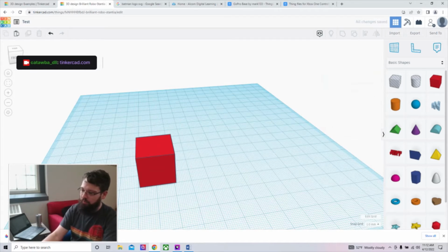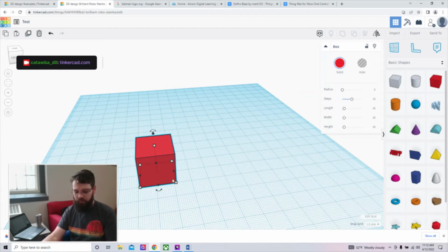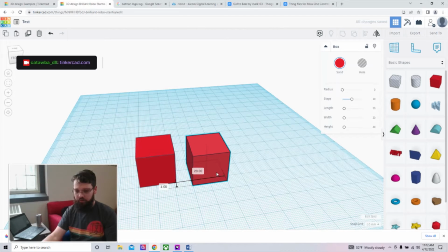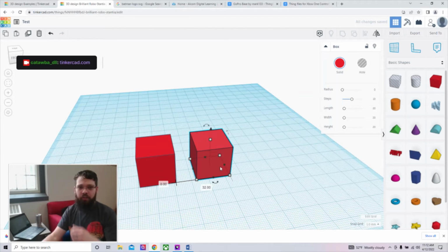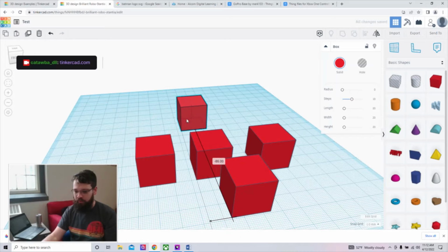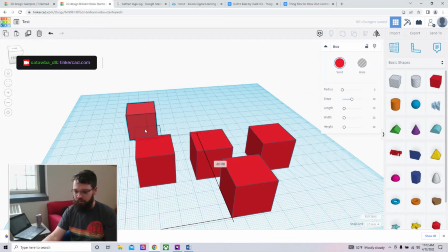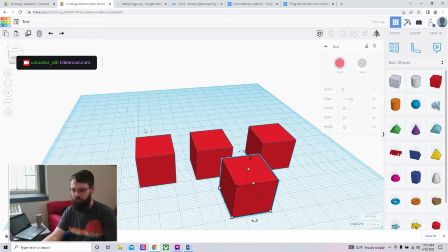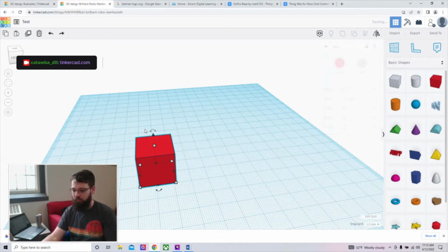Instead of coming over here and pulling multiple blocks, you can hold down Alt and click and make an exact copy of that and move it. Holding down Alt, and it may be different if you're on a Mac, clicking, and still holding down Alt while I'm holding down the click makes you a copy, and you can move it and place it wherever you want to.